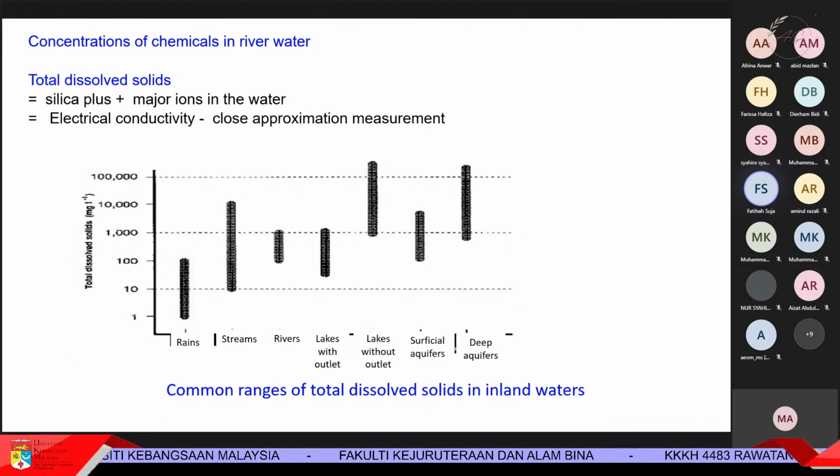Under the influence of major environmental factors, the concentrations of many chemicals in river water are liable to change from season to season, and in small watersheds, which are less than 100 square kilometers, the influence of a single factor can cause variation of several orders of magnitude. So water quality is generally more constant in watersheds greater than 100,000 square kilometers.